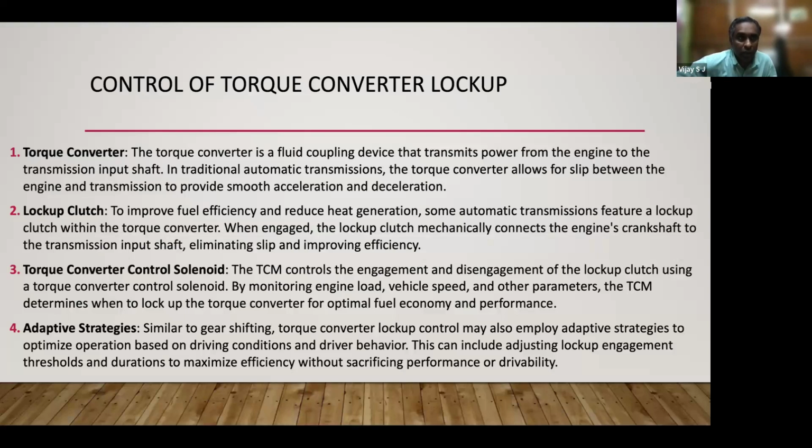So that when you are trying to propel the engine faster, it will automatically keep the clutch engaged until it reaches the next gear, so that the power is seamlessly transmitted. If not, what happens is the clutch totally disengages, and you will feel that lag. So lockup clutch is done to keep the transmission continuously from the engine to the driving shaft or the wheels. So that is the work of the lockup clutch.